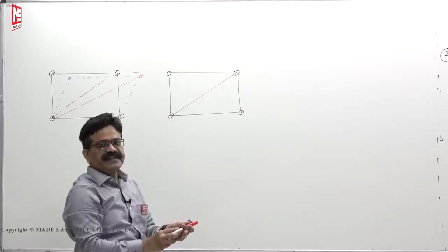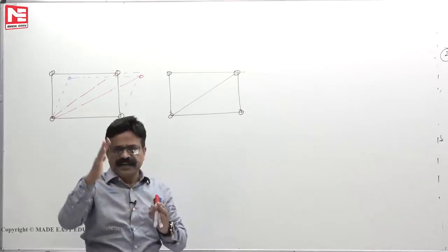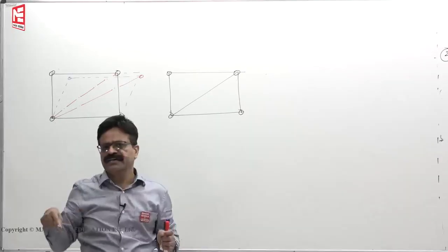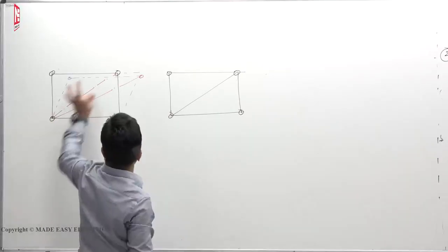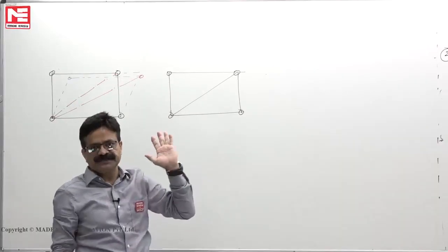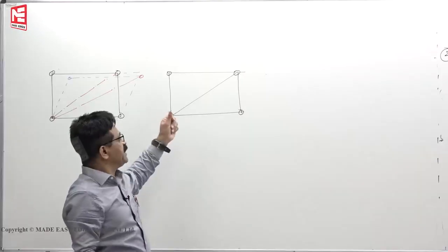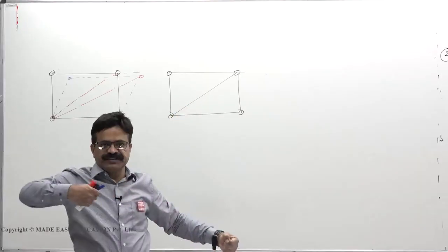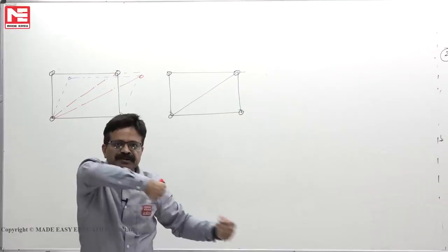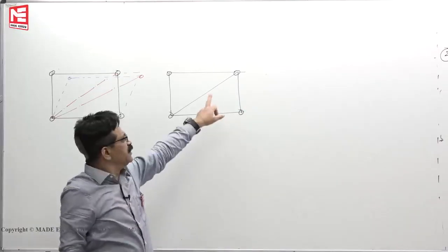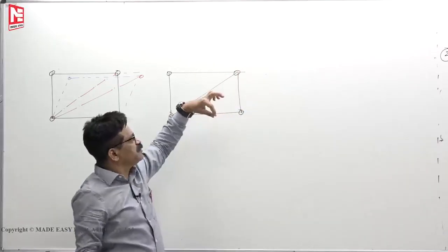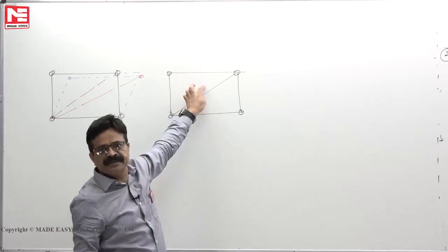In SM, you have studied that pure shear case. If at all one element is subjected to pure shear, one diagonal is under tension, another diagonal is under compression. So there is a member here, this under tension. If at all another member is there, that will be under compression. So in this case, because of this member, it is under tension. When you push it, your push will be resisted by this member by undergoing tension. That means this joint cannot translate without developing stress in this member.